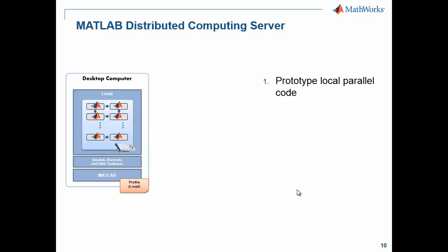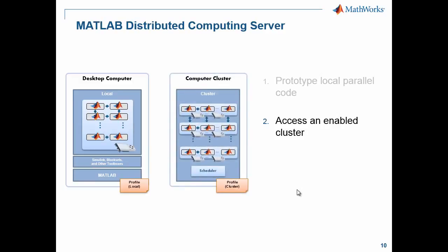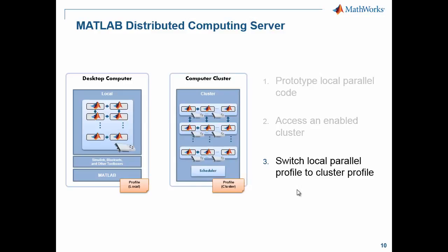Whereas now, for example, you have your job running on multiple workers or multiple threads on your local machine, you can actually make a connection to a remote machine or sets of machines and deploy and invoke multiple sessions of MATLAB on each of those threads as well. Once that's been established, you can switch from your local profile to a cluster profile and interact with your MATLAB session just as you would before, but instead of using local resources, you'll be using remote resources.